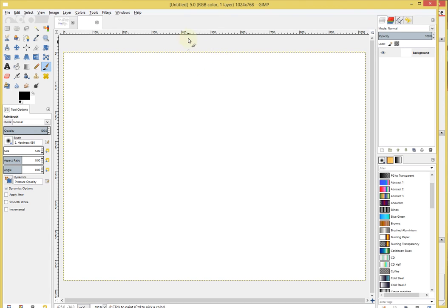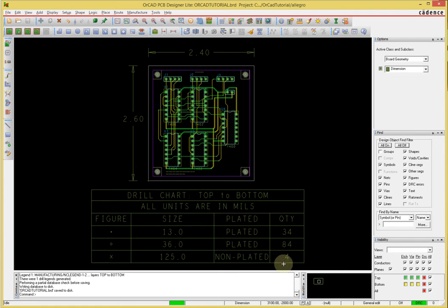The PCB manufacturing industry usually prefers what are called Gerber files, and we loosely call them Gerbers. It's just a standard format. A company defined the original format, and they called it Gerbers. Gerbers is nothing but a file which consists of a vector-based drawing, very loosely speaking. The drawing has no information about whether a layer contains copper, or components, or reference designators, or mounting holes. It's just simply graphic elements.